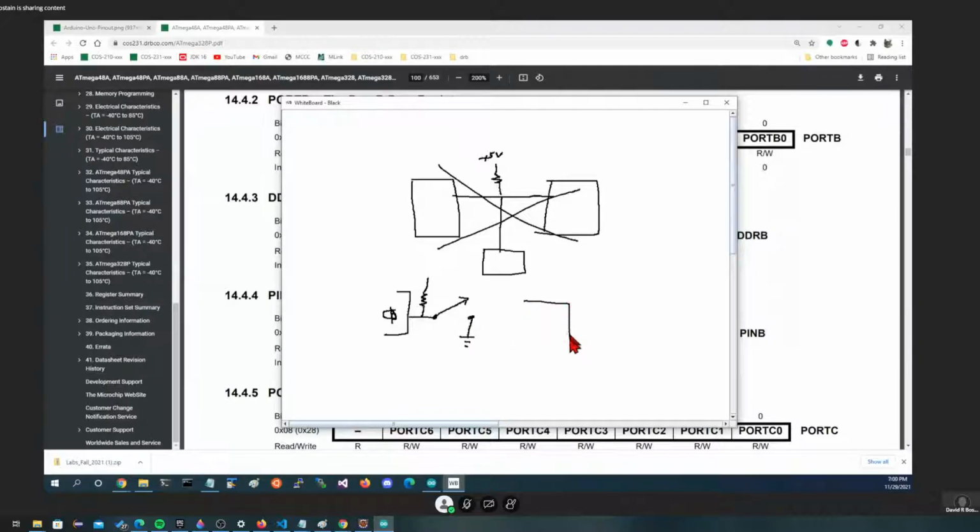What I also have is on all of my pins, I have the ability, let me not draw it this way, this will confuse you. I have the ability to pull it up internally to plus 5 volts. That was those pull-up resistors I was talking about. That's the same as having this here, meaning I can hook things out here that aren't hooked to anything, and when they go to ground, we see a ground, and the rest of the time, because I'm pulling it up to 5 volts, I see the 5 volts.